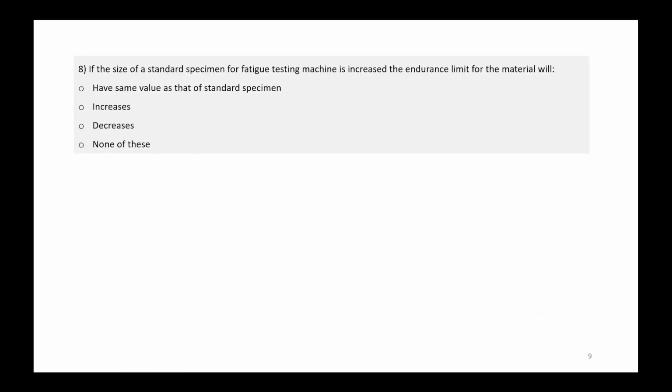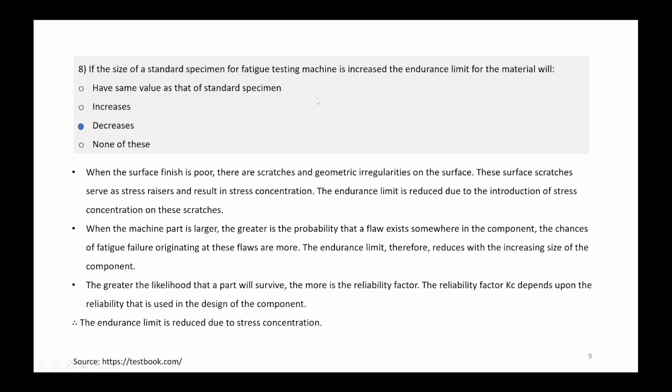In case of the eighth question, you have to tell with change in specimen size what will be the effect on fatigue strength. So endurance limit will decrease with increase in size because the probability of stress raisers will be higher.